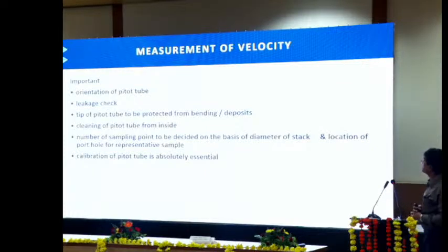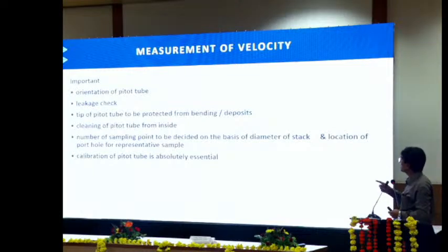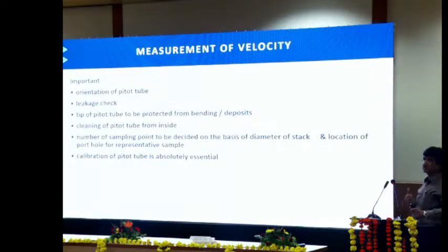Tip of the pitot tube to be protected from bending and deposits, because in the calibration of the pitot tube, it is the tip only which plays a very important role in knowing the pitot constant. Cleaning of the pitot tube from inside: once you are using it on a stack, naturally it's quite likely to get dirty. So after each monitoring, clean it from inside with an organic solvent and then make it ready for the next monitoring.